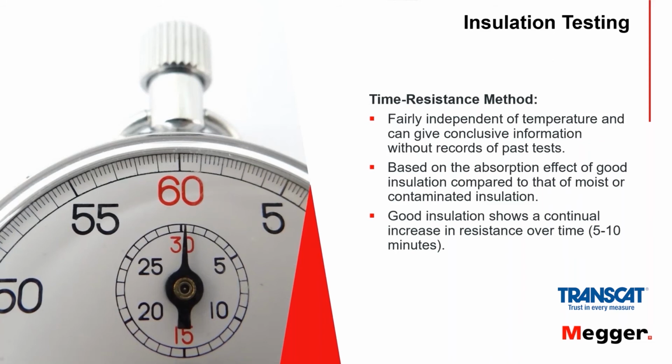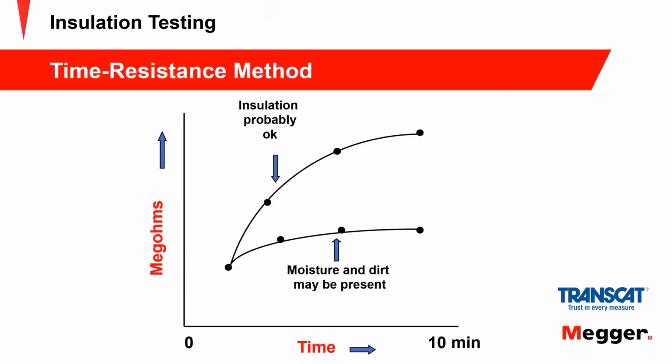And so that gives you more information, gives you more depth in the interpretation of your reading. So this is just a quick representation to show you. Good equipment typically is looking at mostly charging current, and so the readings keep going up. Equipment where there's a lot of leakage current, what you don't want, that holds down your reading. It keeps it relatively flat.